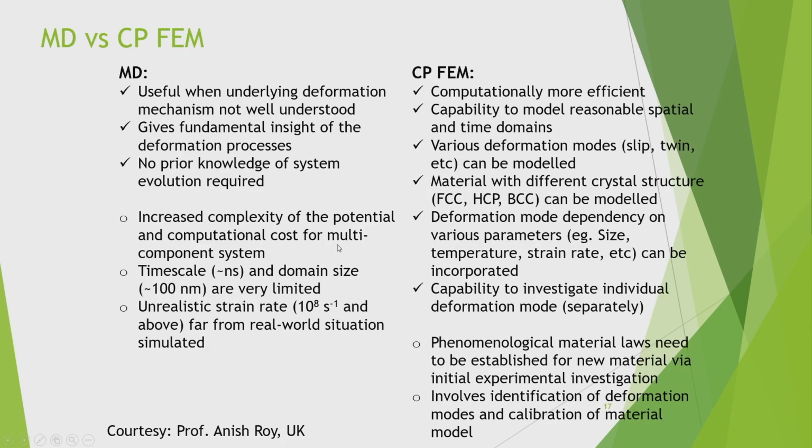So, if we just compare molecular dynamics and crystal plasticity FEM, what are the advantages of molecular dynamics? It is useful when the underlying deformation mechanism is not well understood. It gives fundamental insight into the deformation processes. No prior knowledge of system evolution is required, but the disadvantage is the increased complexity of the potential and computational cost for multi-component systems.